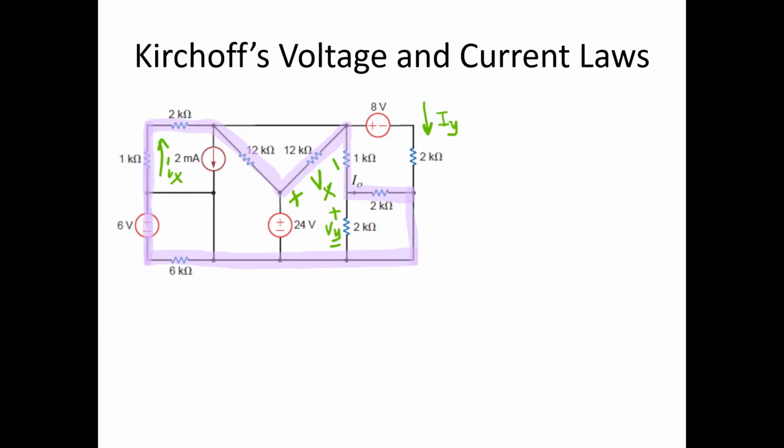However, there are some details in the way that we apply these rules, which I think still deserve some practice and comment. And so I'd like to go over those now in the context of the problem that we had on our third exam, which is now shown up here on the screen. So let's start by first picking one node to which to start our summation. And to make sure that we include all the terms in the summation, I personally think it's a good idea to put a little red dot where we started so that we can make sure that we actually end there when we're done writing our equation.